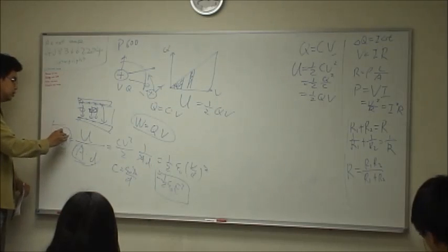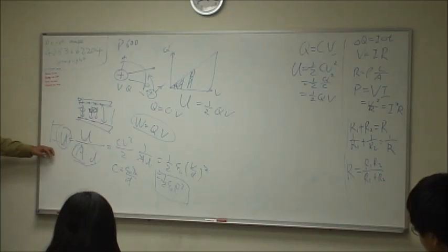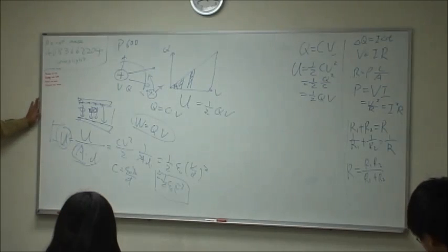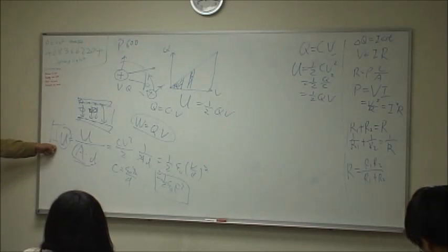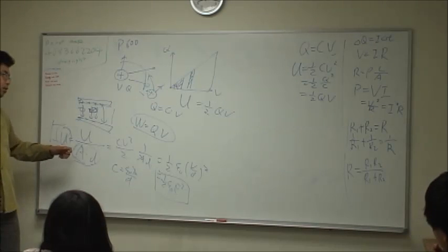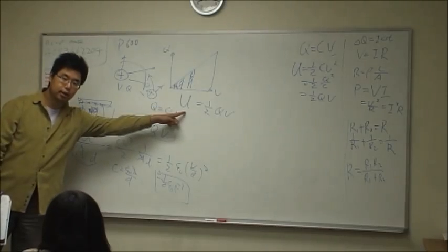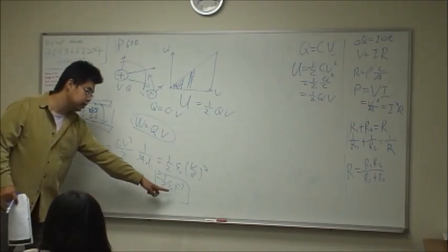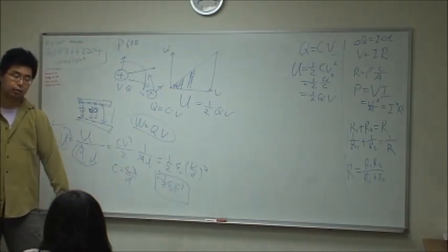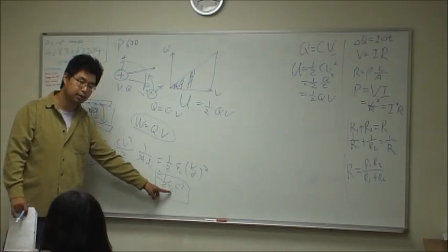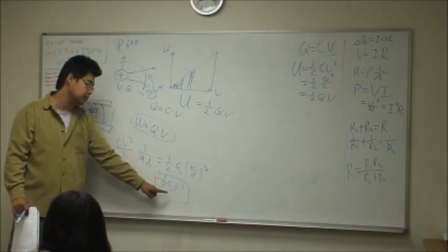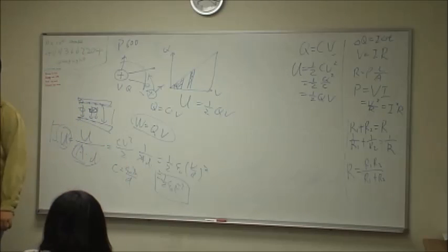Okay, equal to this. I'm not asking you to remember this, but this is a very important concept you need to build up at this moment. Okay, the energy is not stored in terms of charge, but really stored in terms of the electric field. It's proportional to E squared, with epsilon depending on what material you put into the capacitor, and 1/2 is just a coefficient.